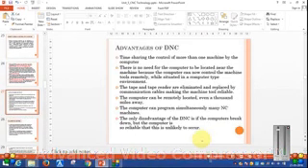What are the advantages of DNC machines? Time sharing and control of more than one machine by a computer. There is no need for the computer to be located near the machines, because the computer can now control the machine tools remotely while situated in a computer-type environment. The only disadvantage of the DNC is if the computer breaks down, but the computer is so reliable that it is unlikely to occur.